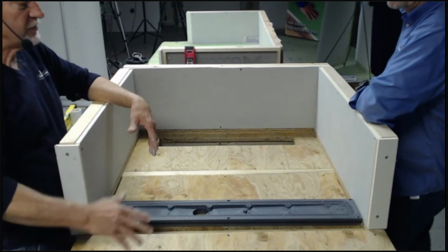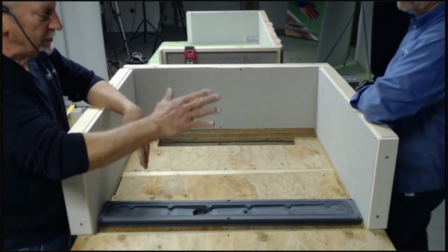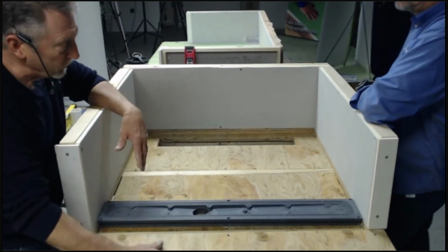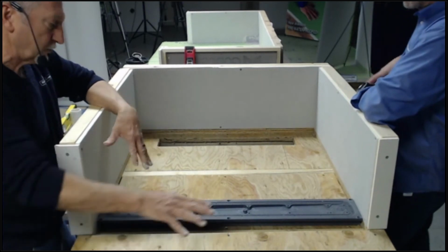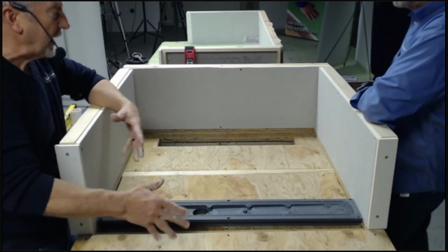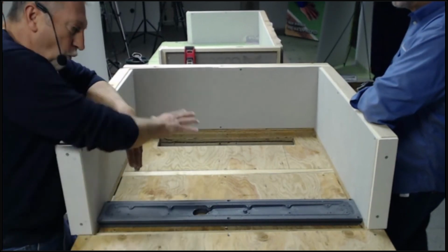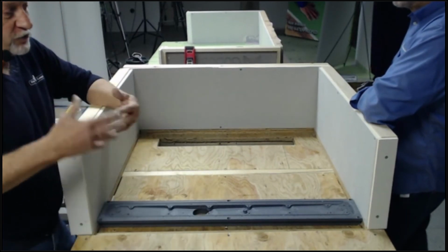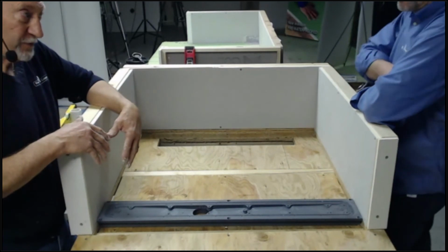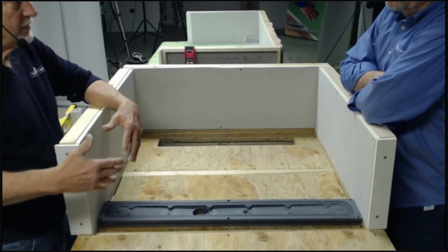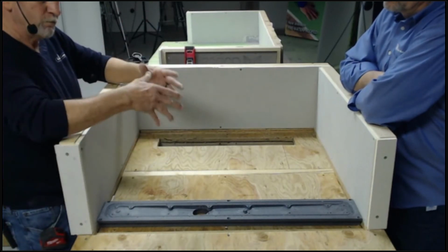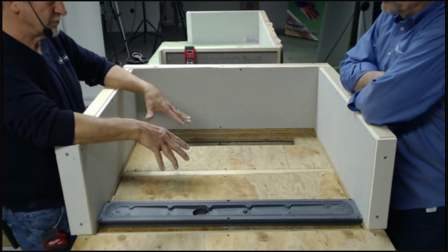Double the overall thickness, and then you've got to transition the pan liner out to your dry space. You're going to have to use a membrane or whatever your dry space has and tie into that pan liner, so you have a waterproof transition all the way out. So it's very challenging to do that. The thin bed method, or the bonded membrane method, and especially with our base, works much easier to achieve that.